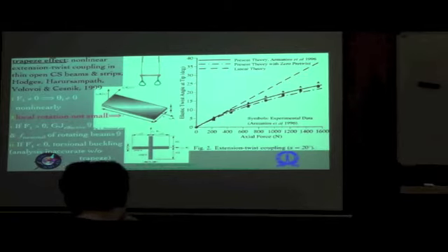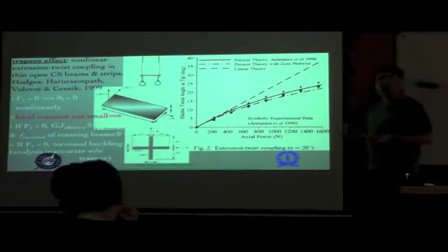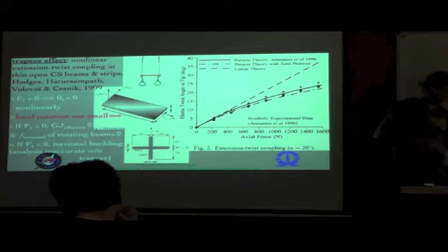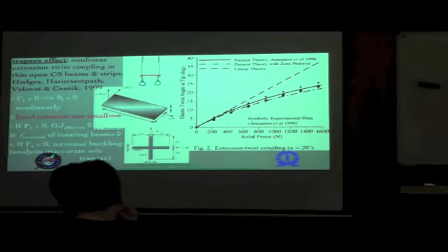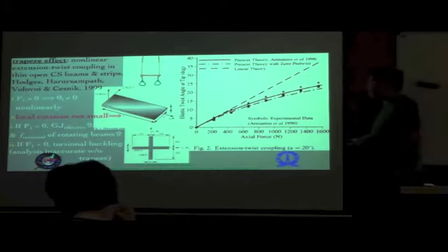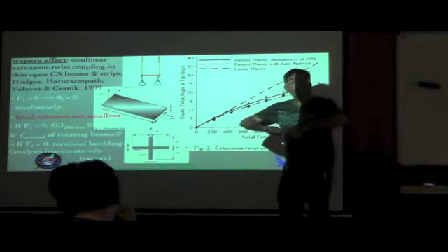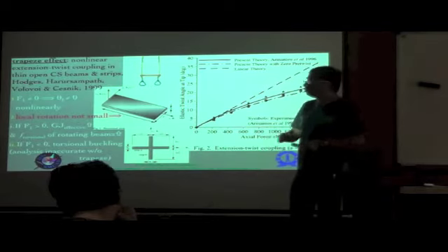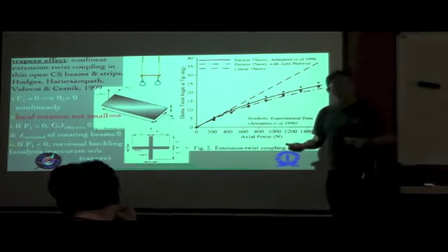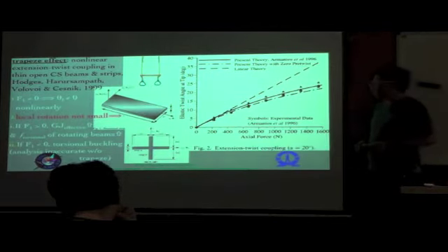So it's the weaker link, and therefore the instability is similar. In both situations it is unstable, whether it's flexural buckling or torsional buckling, but because it's torsionally softer compared to flexurally, it can undergo a large twist at a particular value of the negative axial load.